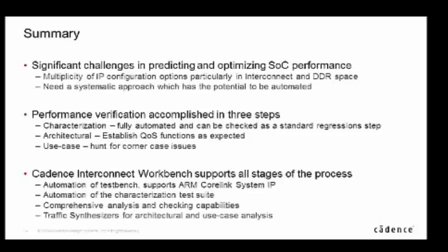Working very closely with ARM, so a lot of the CoreLink interconnect products we support out of the box. So you literally, if you want to configure a NIC-400 or a CCI, you push a button and you get a test bench out with no actual code you have to write yourself. We do support the ability to create test benches with non-ARM interconnect if that's what's required.